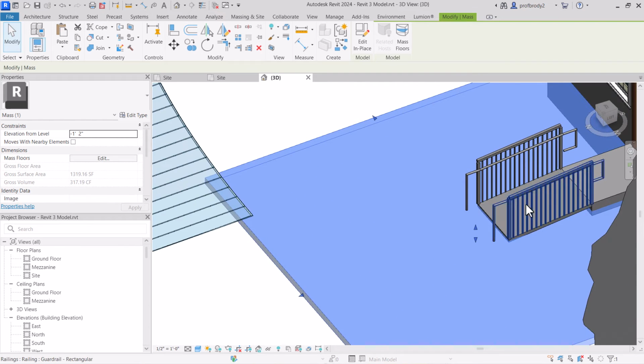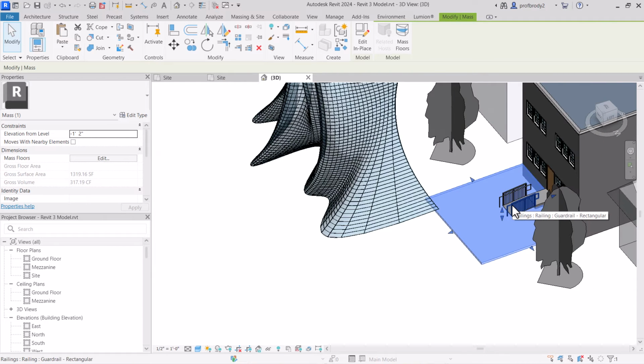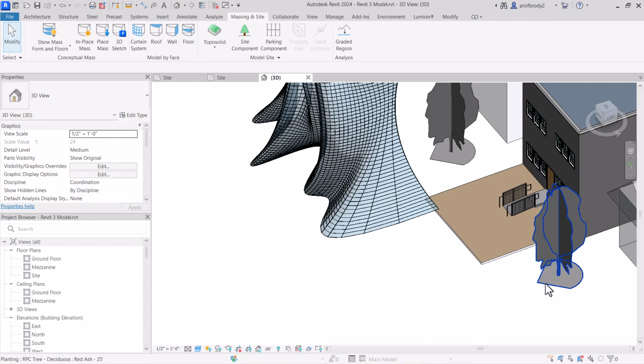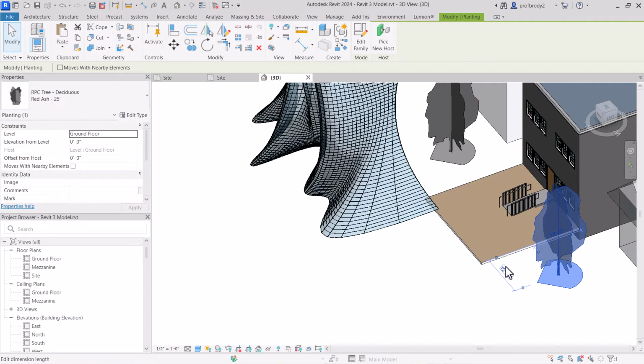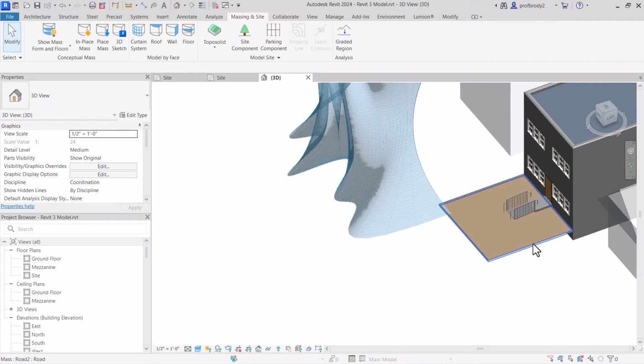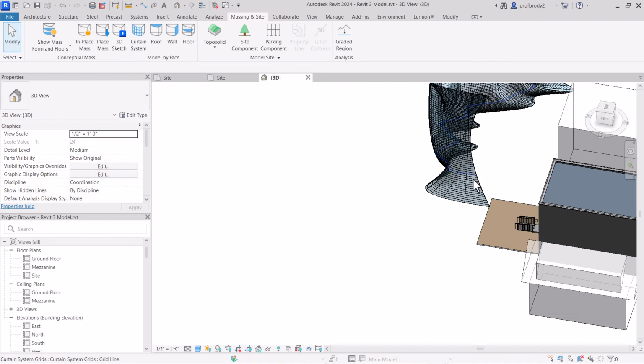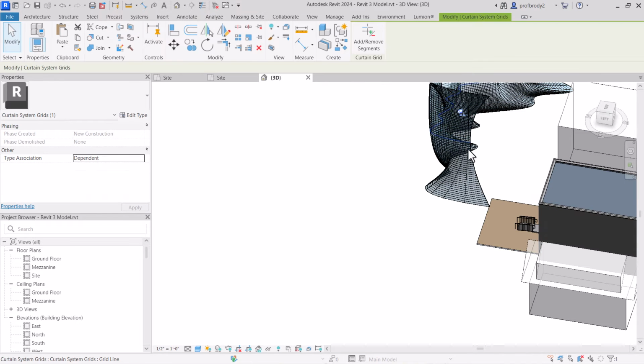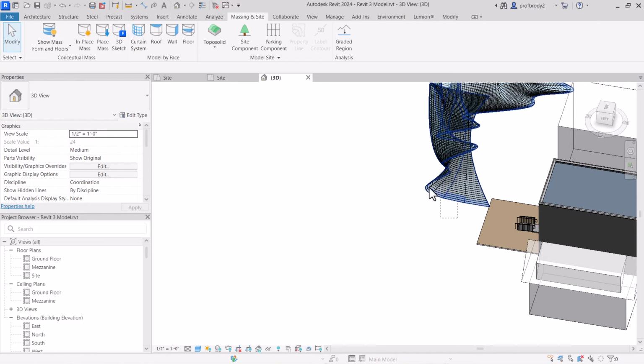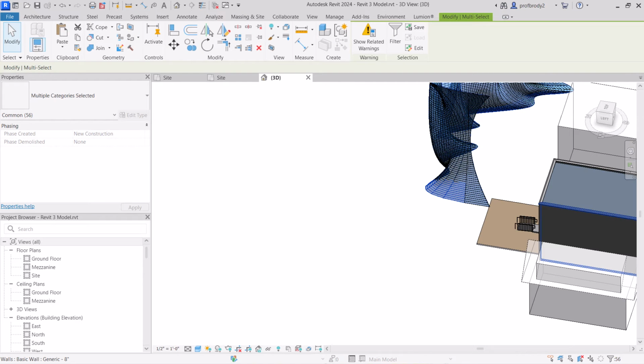Okay, there we go. That looks much better. Anyway, so that's a way that you can just have those hard surfaces that I mentioned. Obviously, any components that are on your site, for example, these trees, these are Revit trees. So I don't want these in here because I'm going to be using Lumion trees, which are much more fun to put in than Revit things. I also probably don't need this weird geometric solid in the background. If you want to keep that in, you can in your projects. But in my case, I think I might find a way to delete that little thing.